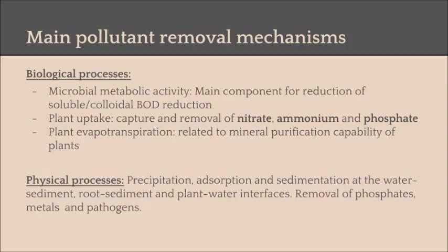The main mechanisms involved in this technique can be divided into three. The biological processes constitute the most important mechanism. They can be either related to the plant or the microbial activity. The microbial activity is the main factor contributing to the organic matter decomposition and performs an important function in the denitrification process of nitrates. Plants perform an important function in nitrogen and phosphorus uptake. The evapotranspiration rate is directly related to the plant uptake of water and nutrients, and therefore to the purification rate of the minerals present in the wastewater.